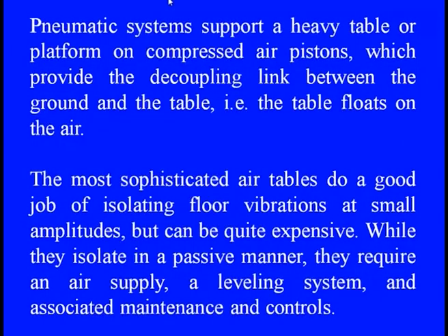Like you see the pneumatic systems which are supporting a heavy table or even a platform on compressed air pistons, and through that we are just providing a decoupling link between the ground and the table. If you look at the real mechanism, the entire table is floating on the air only. So, this air is acting as the passive control feature, and through that this suspension is being provided by the air, and there is a clear isolation of the table from the ground using this compressed air.